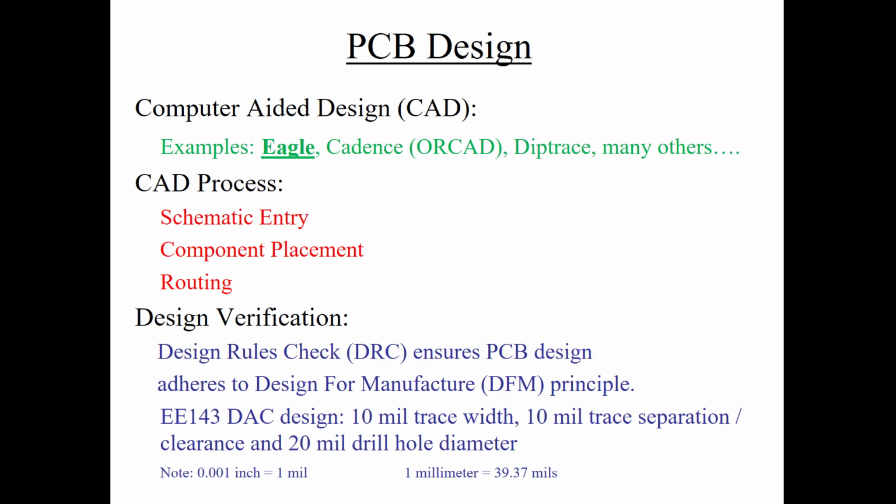Alright, well, PCB design is done with computer-aided design software, CAD software. You'll be using Eagle. These are some others that I have used in the past, but there's many other software packages that you can use to design printed circuit boards. So no matter which software you're using, there's these three basic steps. First, you enter the schematic, and then once the schematic is entered, just by clicking a button, the software will take that logical representation of the circuit, with the symbols and how they're connected, and convert it into a physical representation onto your computer screen.